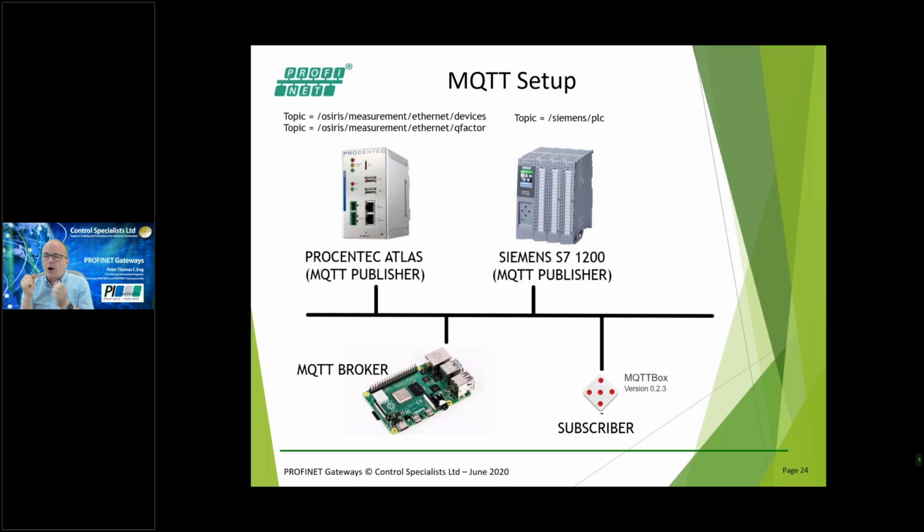So these guys are sat publishing something to the network. We don't have to tell them all of the subscribers. All we do is point them to a broker, and MQTT requires a broker. In this particular case, we've just got a little Raspberry Pi, but we can buy more industrial automation suitable devices. But this is just basically a bit of software that sits on a server PC based system where it is looking for data. It's a very, very simple setup.